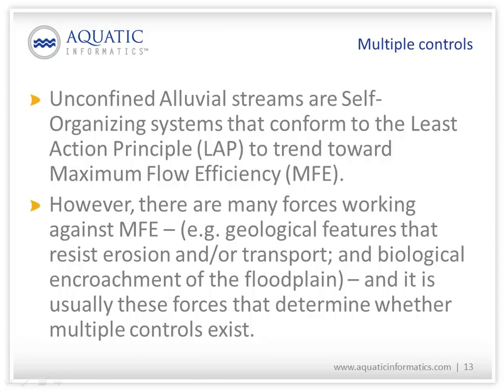So our streams have energy, and they use that energy to rearrange themselves using fluvial geomorphological processes to transport and deposit sediments. The streams are constantly aggrading where they need to aggrade. They degrade where they need to degrade. And it's this channel maintenance that creates this conformance to our assumptions necessary for use of our rating equation.